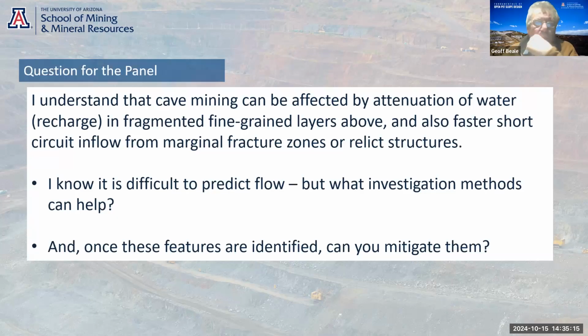Yeah. The other thing that really controls inflow is prior rainfall events and prior saturation. Your water will come through a lot quicker if it's going down flow pathways that are already saturated, and a lot of cave zones will find that early rainfall events in a wet season don't produce much water, and later ones do. If you have back-to-back rainfall events, it's often that the first one hardly produces any water, and the second one, which can be smaller, produces a bunch of water. So pre-wetting of the flow paths is also important.